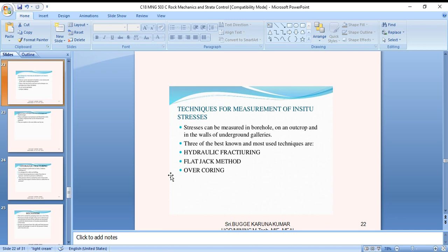In a hard rock mine, the roof and floor convergence may amount to only a fraction of an inch, so the current case for this type is to require a sensing element such as a micrometer head or dial indicator to provide satisfactory accuracy. If the end of the deformeter can be permanently anchored, then an accuracy compatible with the gauge can be achieved. Moreover, this type of installation will have excellent time stability, especially if temperature corrections are made for the expansion or contraction of the rod. However, in many instances, permanent installation is impractical because of possible damage to instruments in many operations.